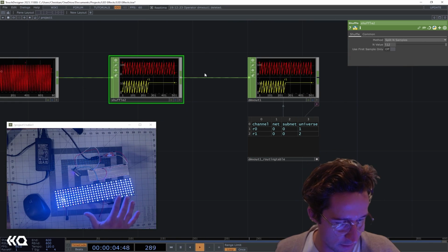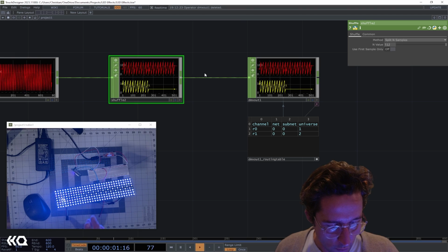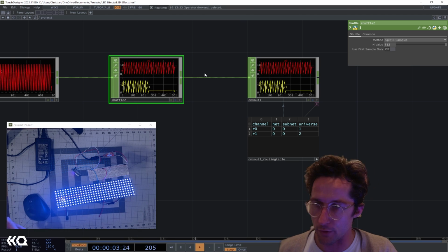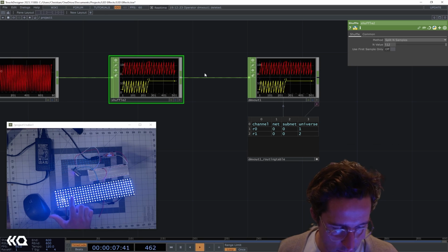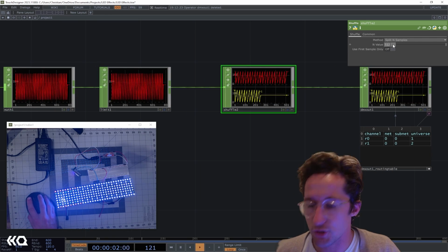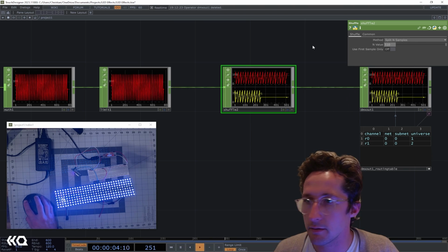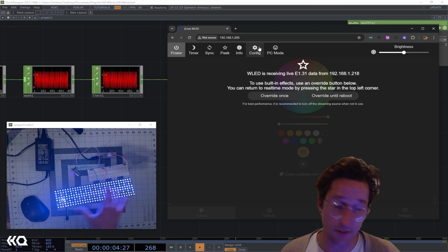So now we can see there is some mismatching of the LEDs. It looks like we're not combining the red, green, and blue channels to get a pure white. If you can see that, there is a little bit of red. And if we go and change this to 510, that will fix it. And the next problem we have over here is this serpentine pattern.